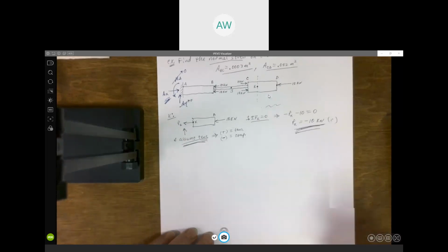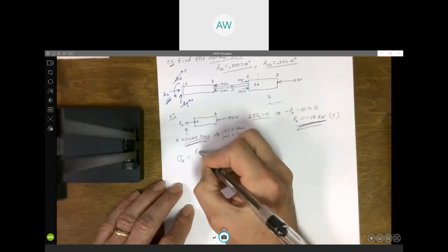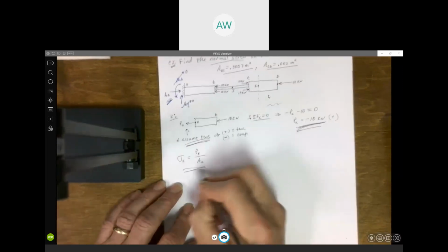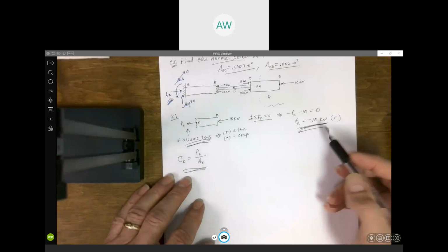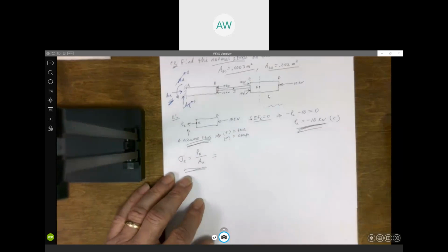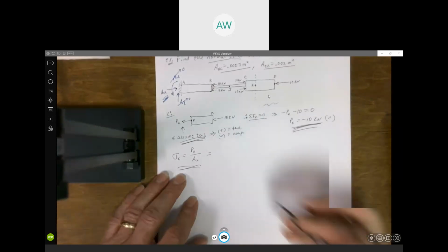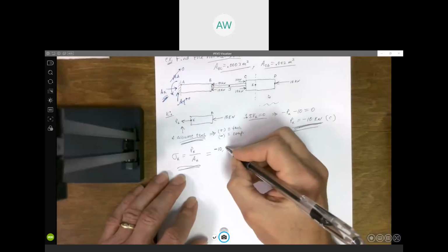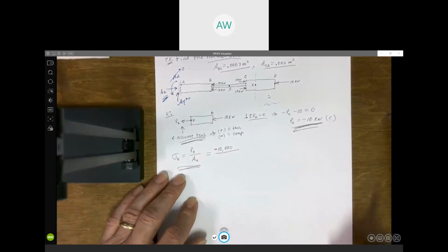All right, so let's calculate the stress. We want the normal stress there at K. We just take what that axial force is and divide by the cross-sectional area there. Well, we calculated that force was, again, 10 kilonewtons. And again, I'm going to use plus or minus for tension and compression. So this would be minus. And it's kilonewtons, so I'm going to go ahead and convert it into newtons. So that'd be minus 10,000 newtons.